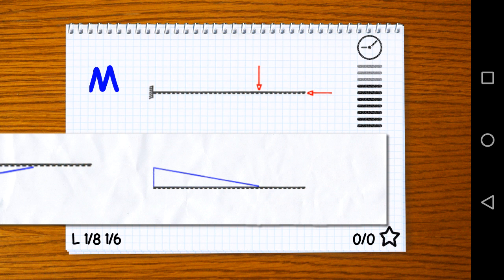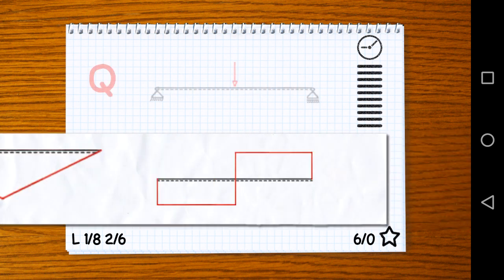So with the single load we have here on the cantilever beam, the beam will bend downwards if we think about the deflection line, causing tensile stresses to be on the upper side of the beam of the cantilever. And what we say is that the moment is on that tensile side. So basically upward, a negative value, and from the end of the cantilever to the single load, we couldn't have any moment there.